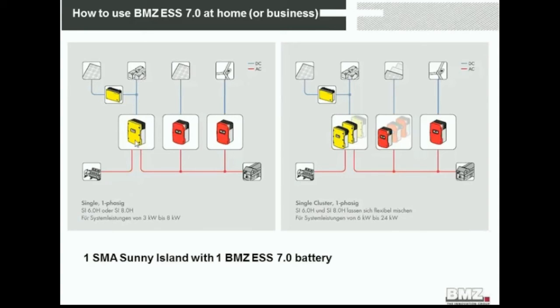In this case, it's an SMA Sunny Island, which is a very good inverter, I would say. The biggest battery inverter at the moment. It can be connected to the grid, for example, when you have only one Sunny Island and one or more batteries. It can be one phase.